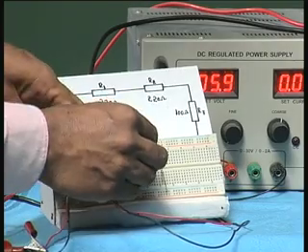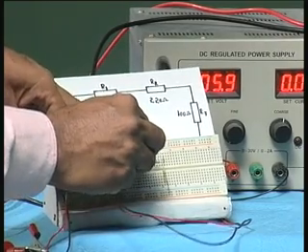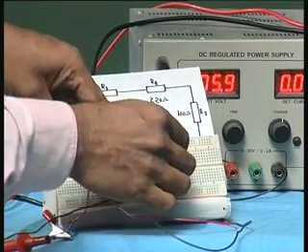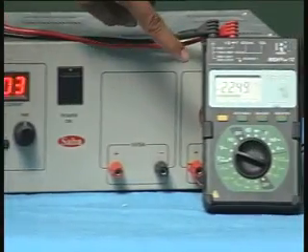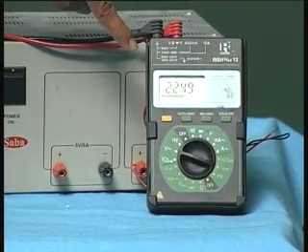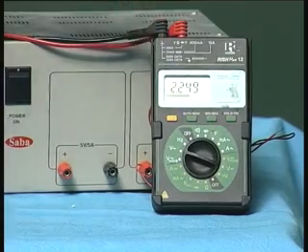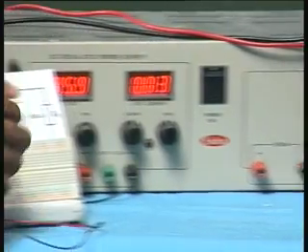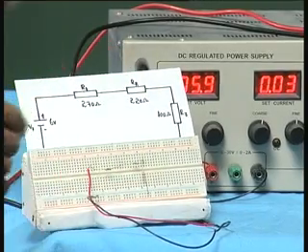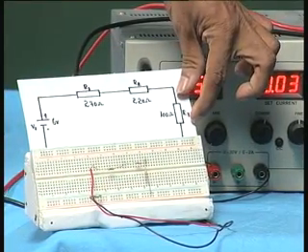So, I connect the positive to one end, I connect the negative to the other end. Now, let us read what the voltage is. The previous one was 2.77, now it is 2.24. So, if you add them together, they come to approximately 5 volts, and now the last resistor is R3,